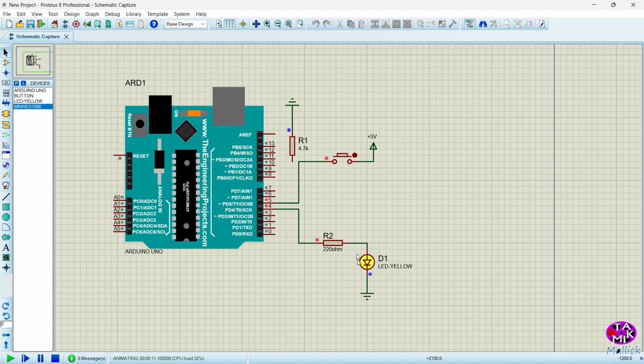It's always in the on state because of noise. This will happen exactly in real life. So we must connect a pull down resistor here. Let's connect it again and see the result. You see, now it's working as I wanted.